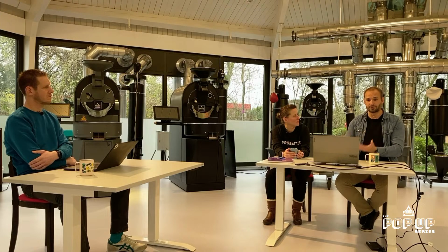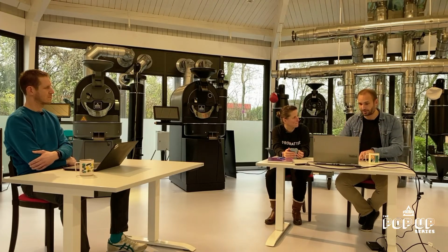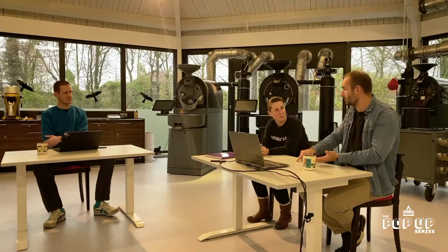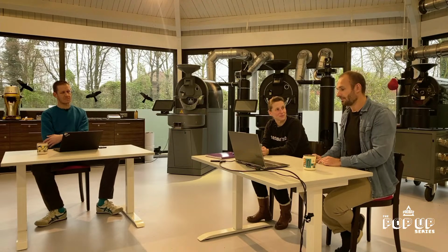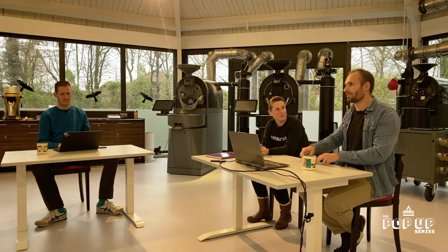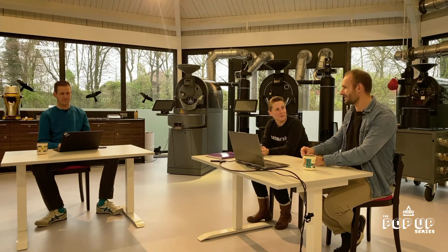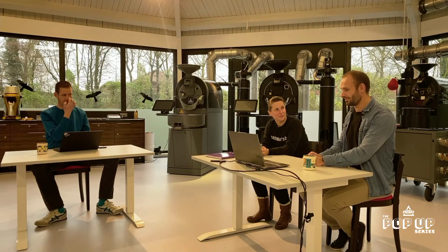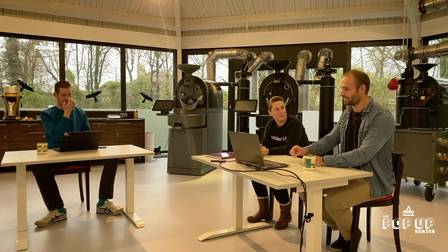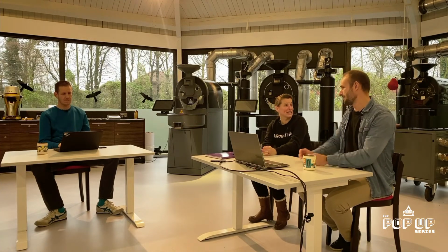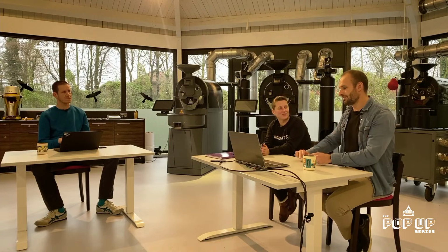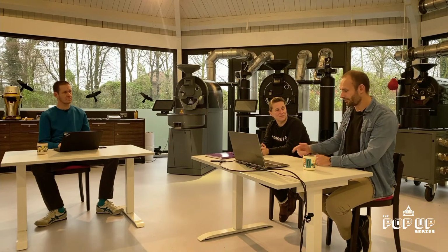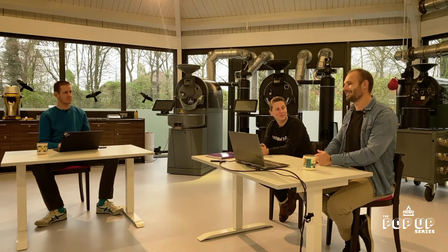So that's why we use the product temperature as our control, because if we overshoot, which you see as a difference in rate of rise, we can come back to the product temperatures, which is what we actually wanted in the first place. So what the controller is doing right now, it's really trying hard to hit the rate of rise, because if it hits the rate of rise, it hits the product curve. Yeah, exactly. And controlling the other curve just leads to unintended effects, I would call that.